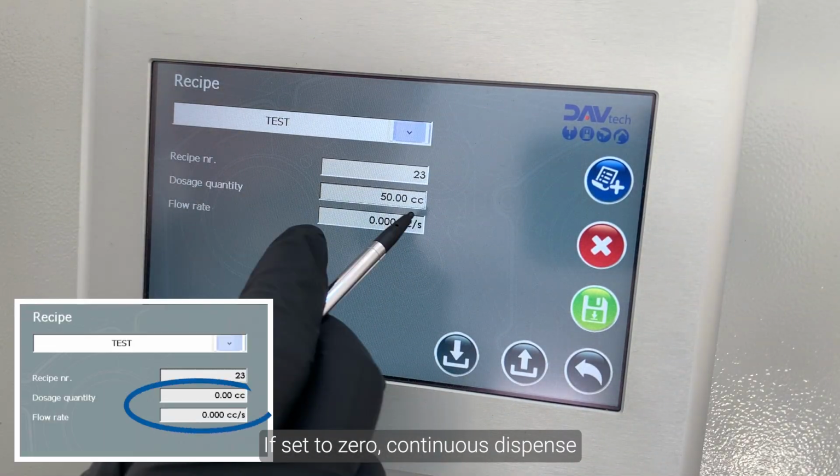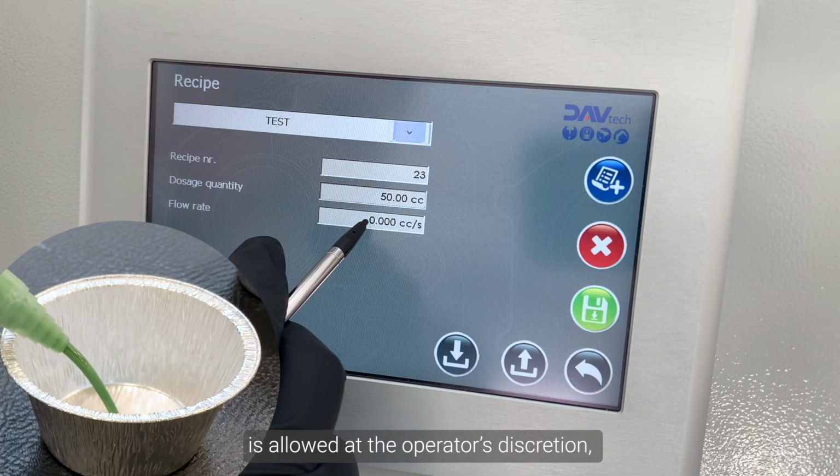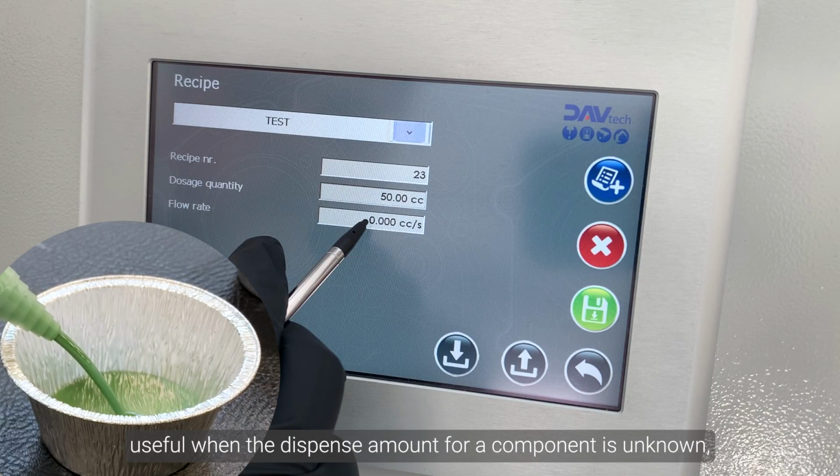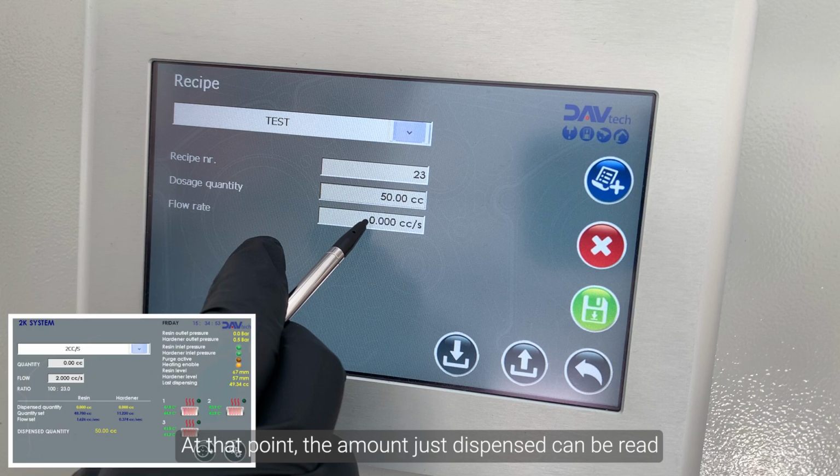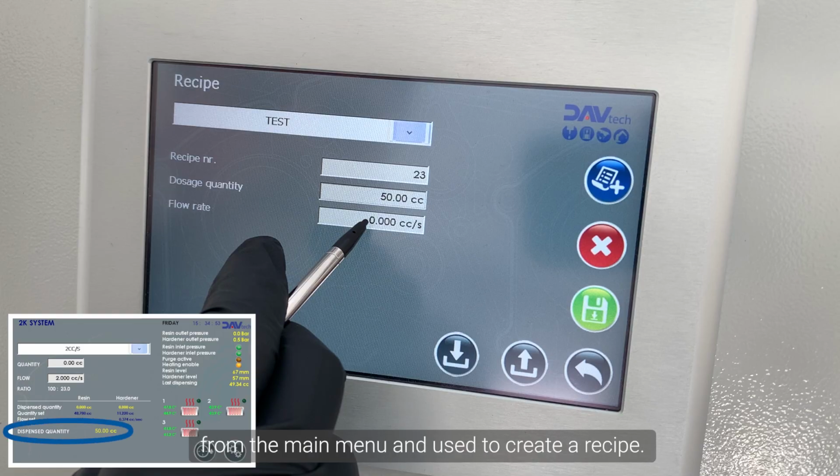If set to 0, continuous dispense is allowed at the operator's discretion, useful when the dispense amount for a component is unknown, as it can be determined empirically by observing the fill level. At that point, the amount just dispensed can be read from the main menu and used to create a recipe.